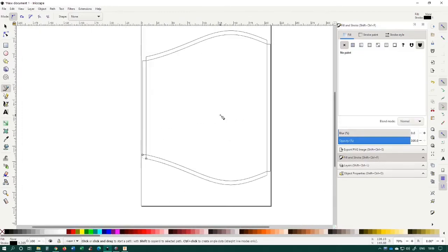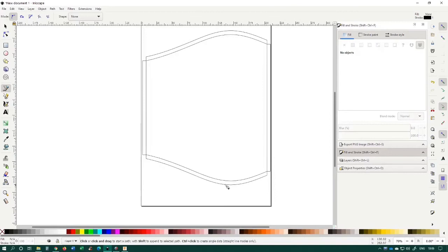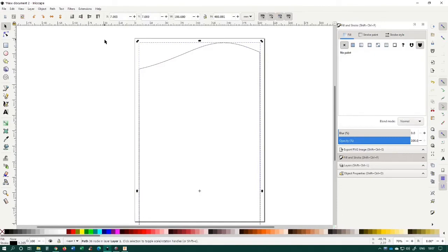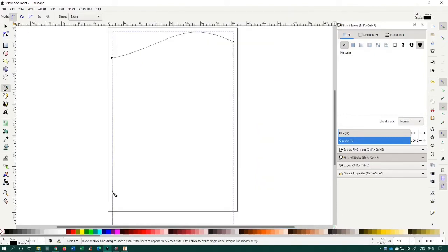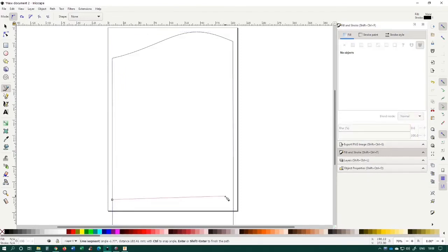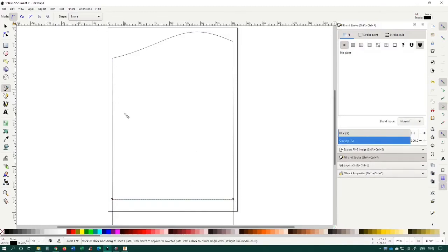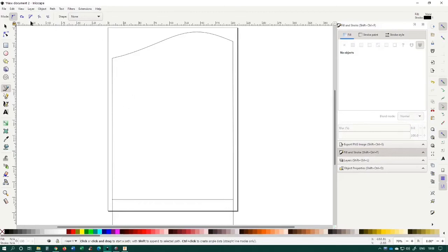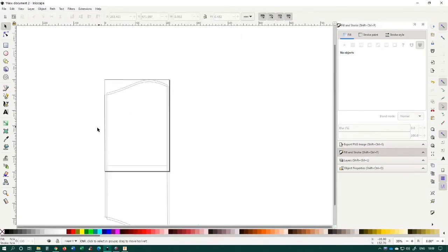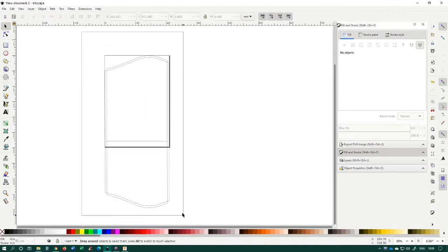When you've finished, it's just a case of printing out your pattern to use for cutting your skirt sections. Now, depending on the size of your model, you may find the skirt sections do not fit onto a single page. In this case, when you import the section, simply add extra registration lines or marks and then do the same process. But when it comes to printing, you'll need to move the pattern around on the page such that the registration marks stay visible. Then print off the pages to make a complete pattern by overlapping the pages, lining up the registration marks.